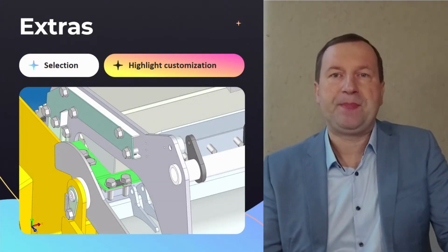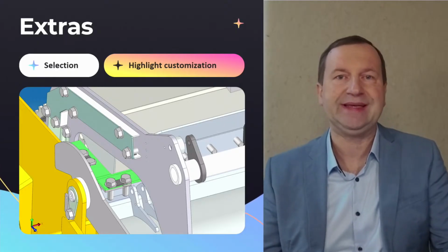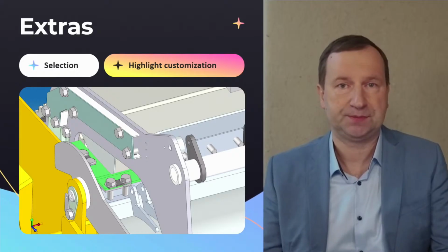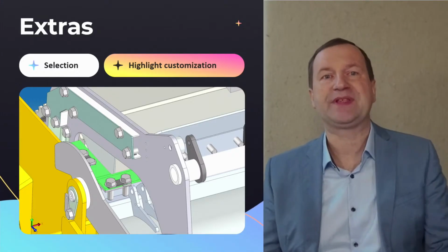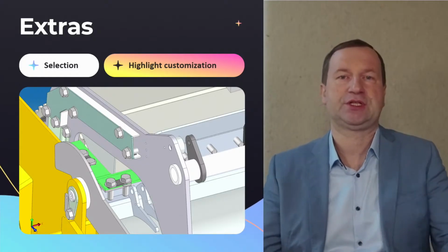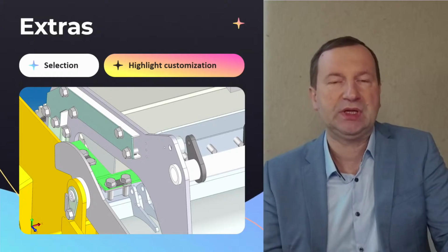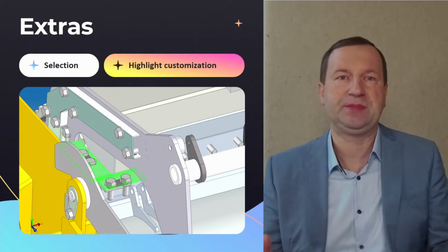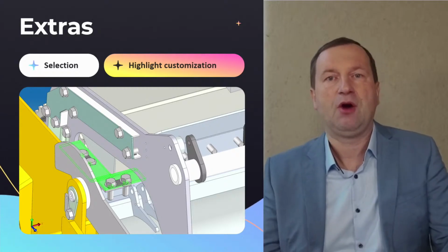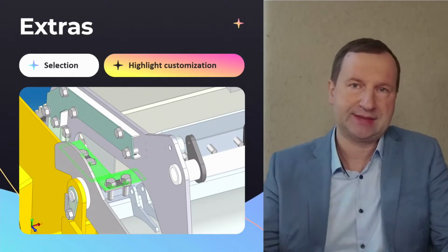Selection is often paired with highlighting, as selected objects usually need to be visually distinguished. Visualize SDK offers this functionality and allows customization of highlighting styles. In addition to basic color changes, you can control the visibility of edges and faces or render highlighted objects or object parts on top of others.